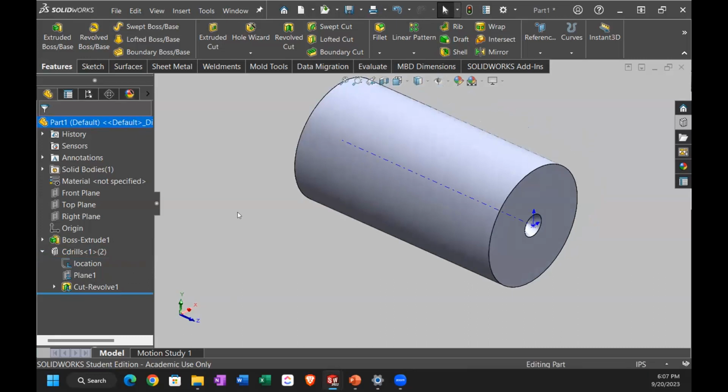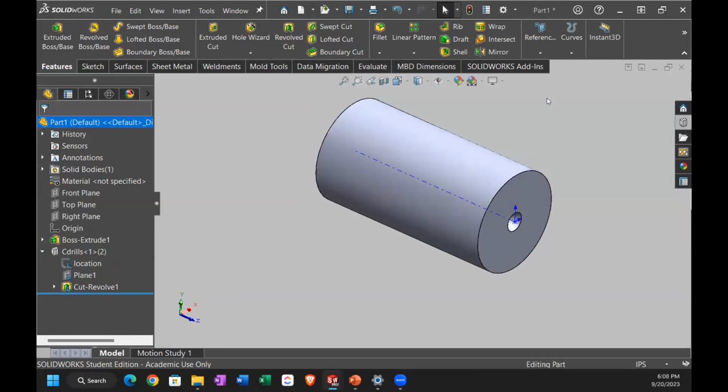So going into the drawing then, I would go into my favorites and put a note on here. Number 2 center drill as needed. If this part isn't long enough or the manufacturing process isn't an advantage, I'm not going to require it, but it is available if they want to use it.